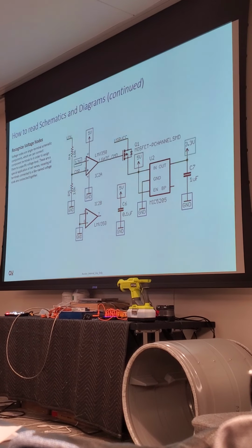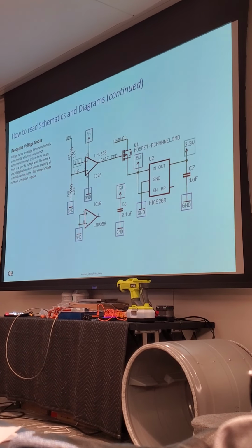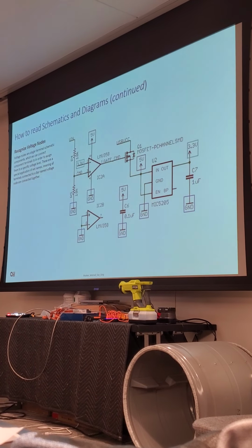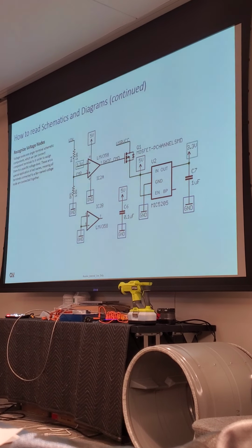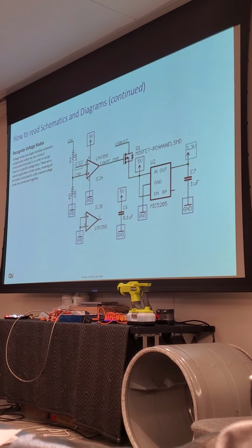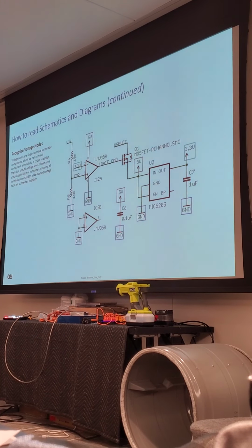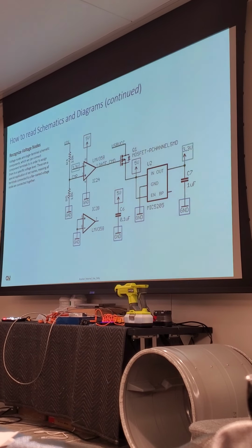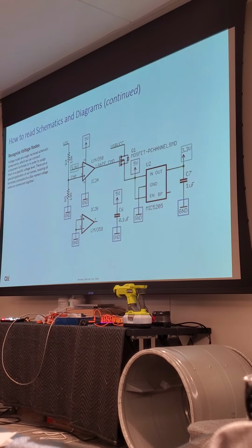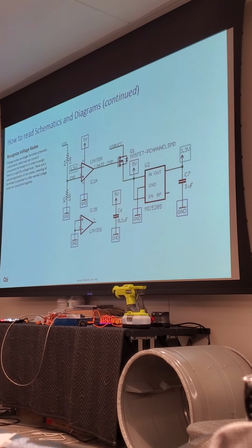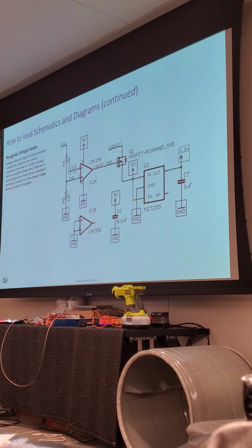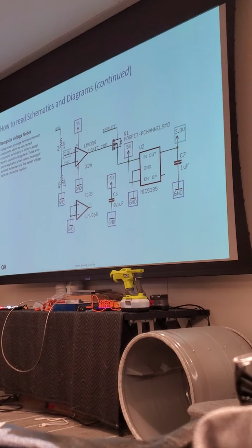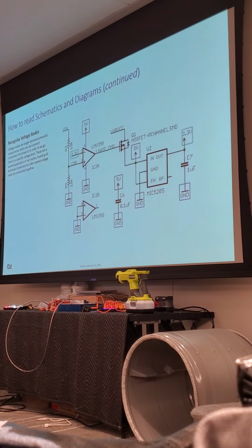So when you're testing your voltages on the fans on a refrigerator, you go from one pin to ground. You go from the next pin to ground and see what your voltage is to that fan. If you're doing the feedback, you still go from that next pin on your feedback to your ground. So if it's the connector CN30 on the refrigerator, you're going from 13 to 15 to get your primary voltage going to the fan, which is 7.62. Then you go from 13 to 17, and you get your feedback voltage, which is going to be anywhere from 2.3 to 2.7. That's extremely common for all of Samsung's products that have DC circuitry for their fans.